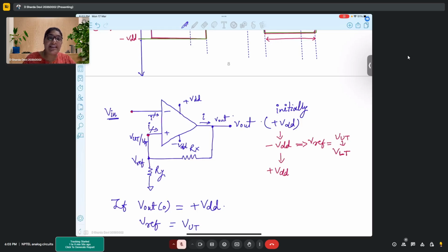But you are not providing any additional input to it. Any sort of sine wave, square wave, or even any sort of DC in the input. So oscillators don't take any input. What they do is they start with a certain noise which is always present in a circuit. It can be any kind of noise, and it picks up that noise, and that particular oscillator circuit has a resonant frequency present.